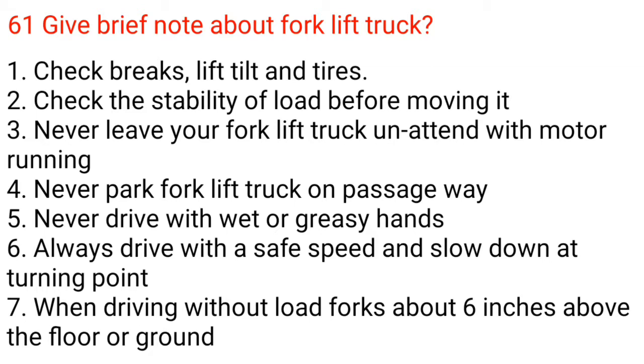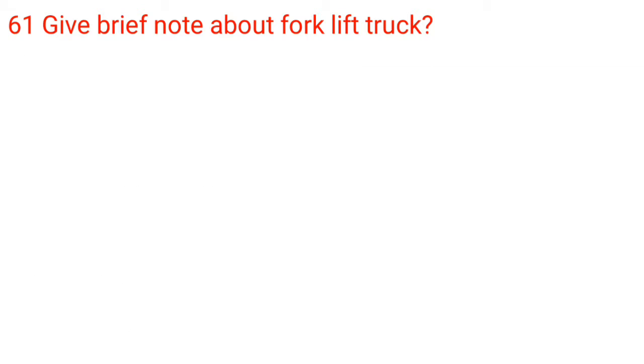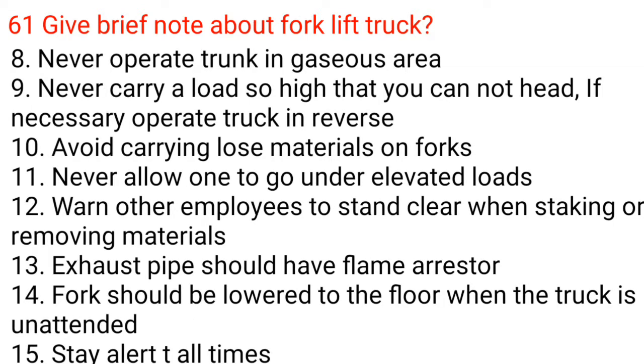7. When driving without load, keep forks about 6 inches above the floor or ground. 8. Never operate truck in gaseous area. 9. Never carry a load so high that you cannot see ahead; if necessary, operate truck in reverse. 10. Avoid carrying loose materials on forks. 11. Never allow one to go under elevated loads.